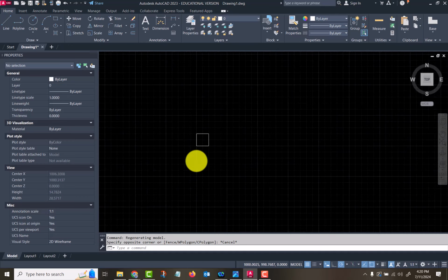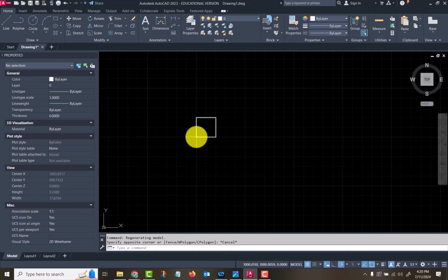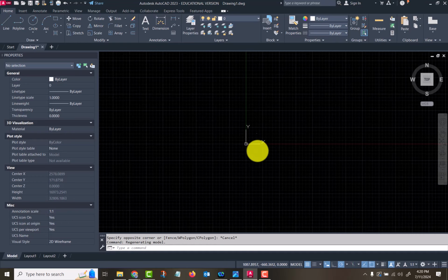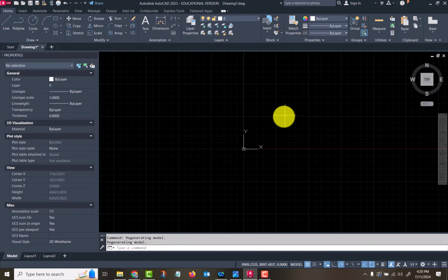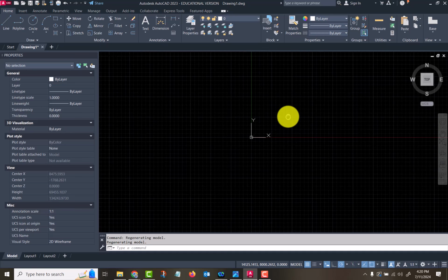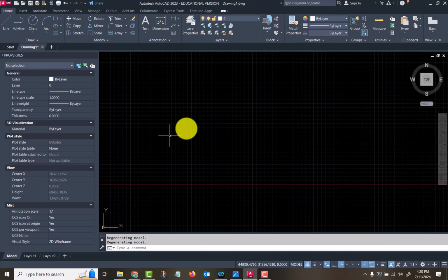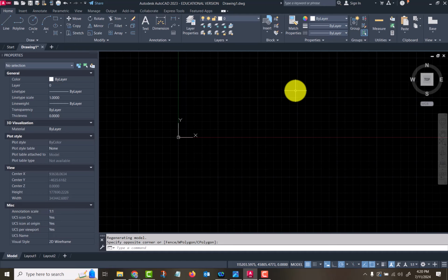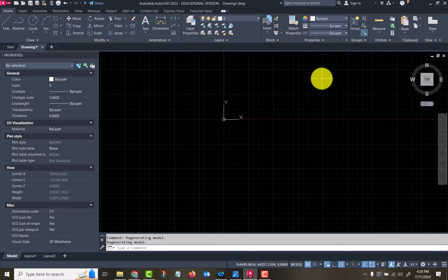The problem is that corner of the rectangle is at coordinates 1000, 1000. And if you open your file up, depends, you may be zoomed out really, really far, or for whatever reason you started drawing way over here, and then you can't see your object. Like you're rolling your mouse wheel, you can't find it.